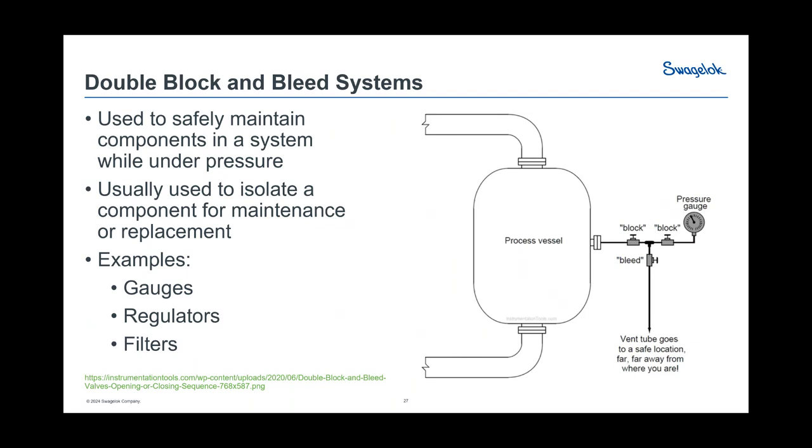In almost every case in your hydrogen system, there's a problem. If you crack into the system, you're going to let air in, and air has oxygen in it, and that's a problem. So what you need to do after you've done maintenance is nitrogen purge that system down before you reintroduce hydrogen. So the recommendation is you shut the whole system down, bleed down the hydrogen, then go ahead and do the work and then refill it.